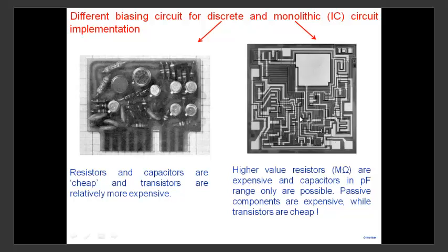Capacitors which are feasible are in picofarads: 10 picofarad, 20 picofarad maybe, or 1 picofarad. If you want capacitors of that magnitude, it's okay, you can use them. But any larger values, nanofarads and microfarads, are out of the question.